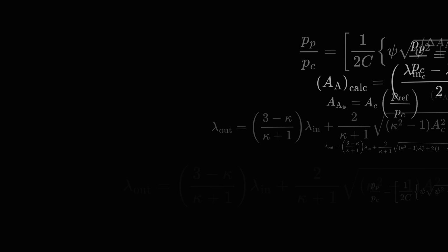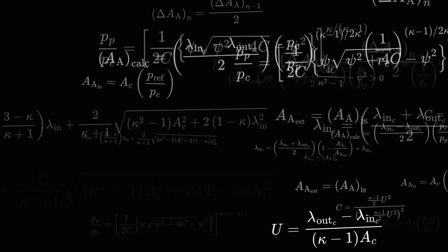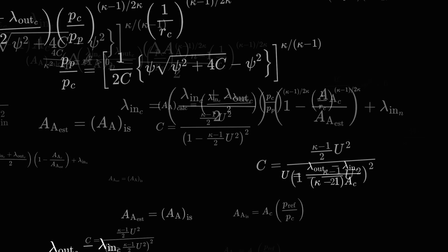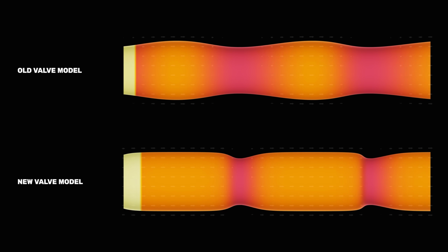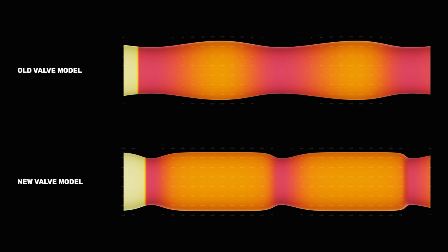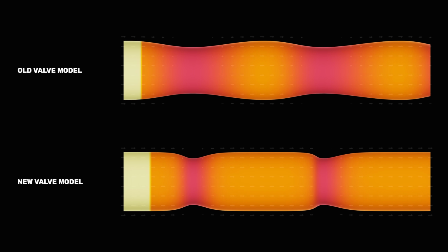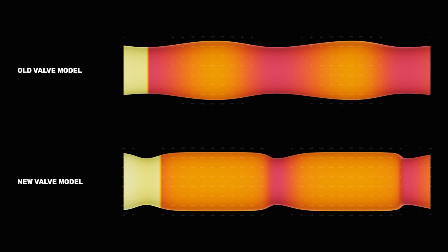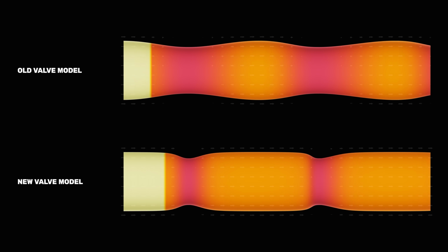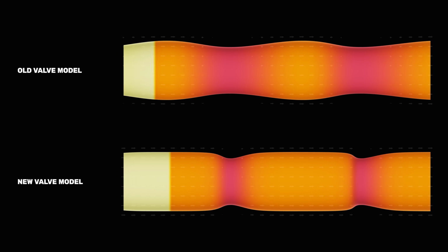The model I replaced it with is a classic valve model described by Benson, one of the forefathers of engine simulations. Benson also gave an algorithm to solve the nonlinear equations of this model, but I couldn't get it to work well, so I created my own algorithm with better performance and convergence properties. I say this very casually, but this on its own took over 100 hours of work, and I might discuss this algorithm in its own video at some point. So here's what it sounds like with this new valve model.